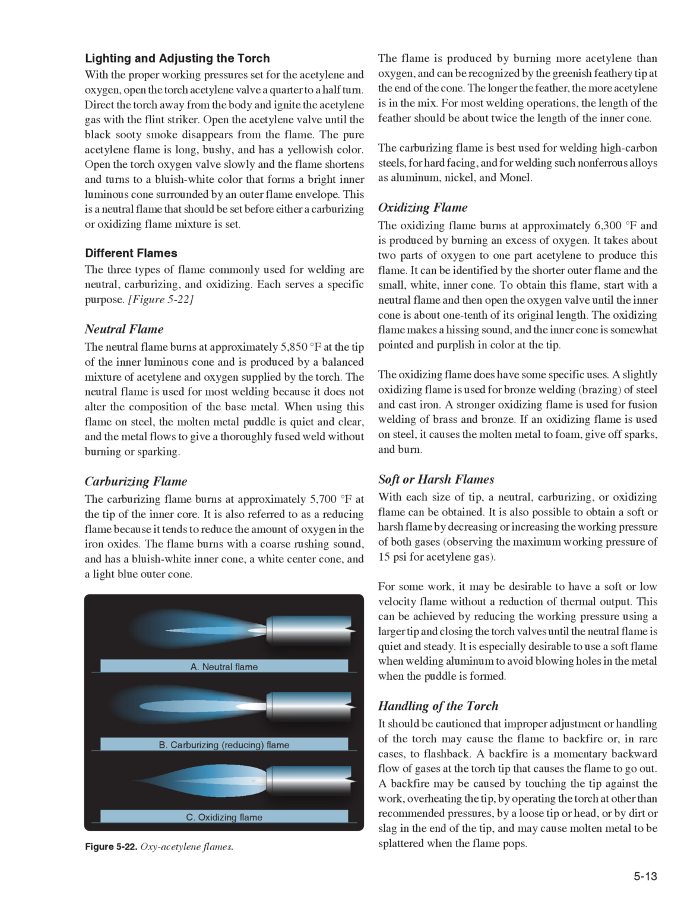A flashback is dangerous because it is the burning of gases within the torch. It is usually caused by loose connections, improper pressures, or overheating of the torch. A shrill hissing or squealing noise accompanies a flashback, and unless the gases are turned off immediately, the flame may burn back through the hose and regulators, causing great damage and personal injury. The cause of the flashback should always be determined and the problem corrected before relighting the torch. All gas welding outfits should have a flashback arrestor.